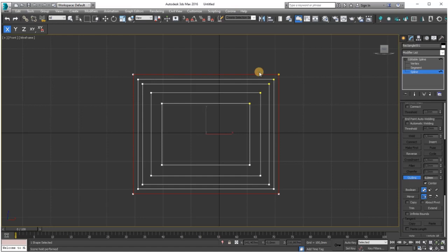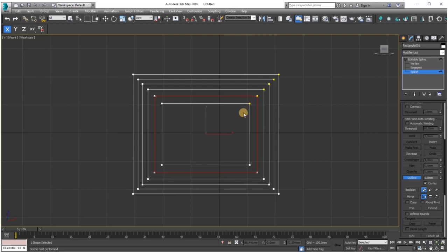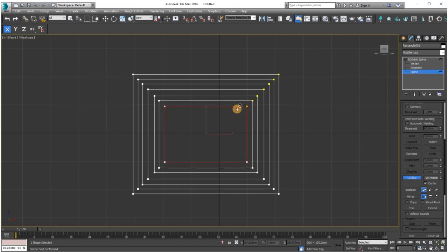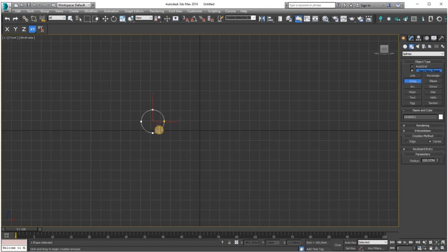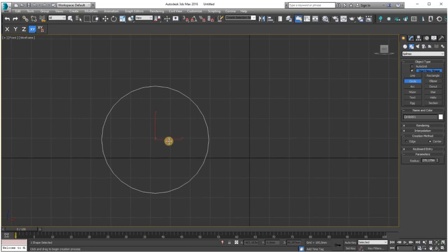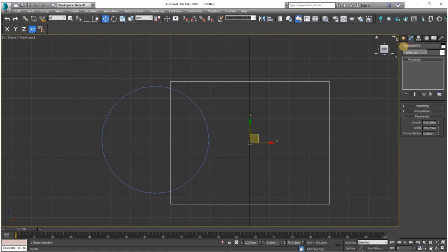When center is on, the original spline and its outline moves away from an invisible center line by the distance specified by dragging operation or by value specified for the spinner on the right of outline. Boolean combines two splines. It alters the first spline you select and deletes the other one. There are three types of Boolean operations available. In table, summarize this operation.